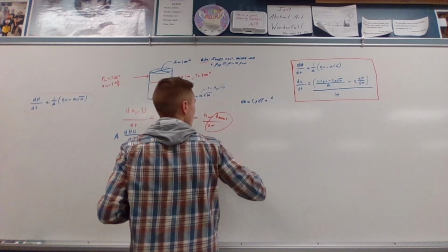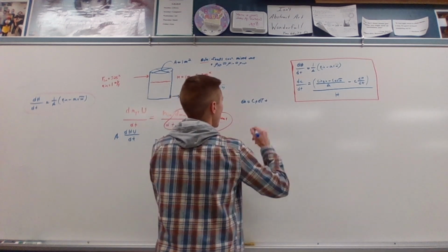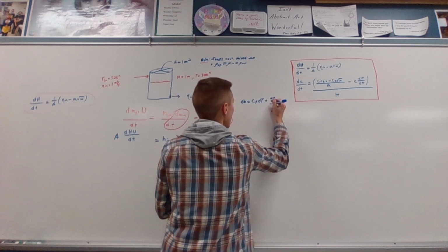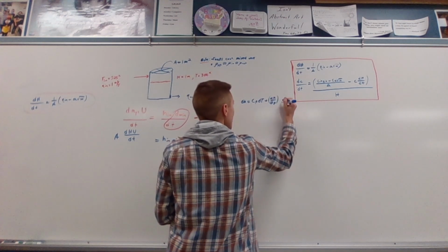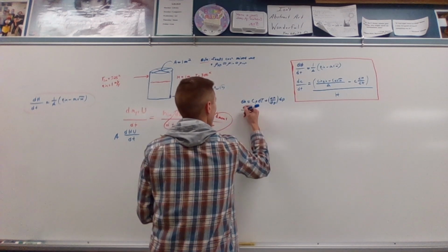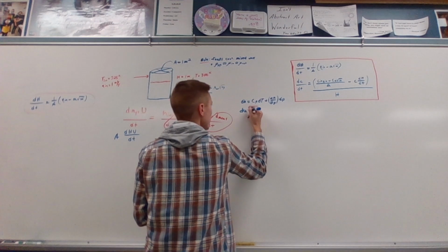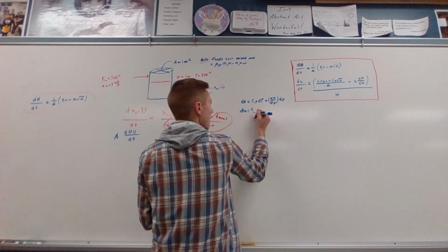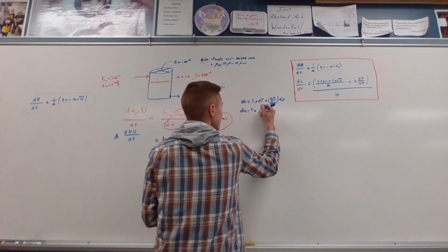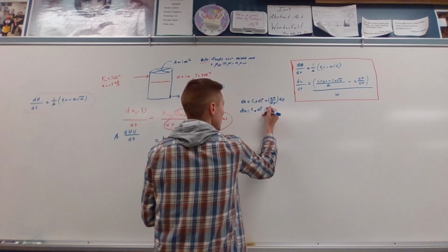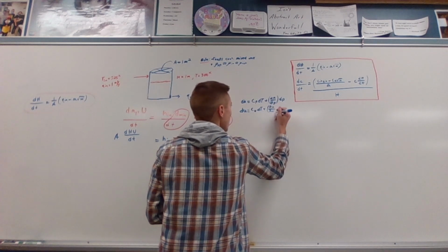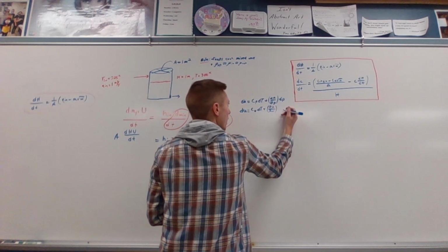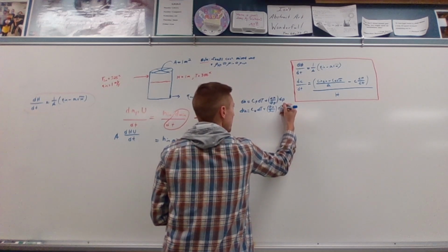Our dependence in this case is the partial derivative of enthalpy with respect to pressure times a small change in pressure, and a small change in internal energy is equal to a similar equation: a heat capacity at constant volume with respect to temperature plus its dependence, which is also similar, the partial derivative of U with respect to volume, and that is times a small change in volume.